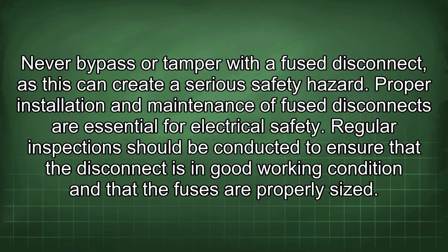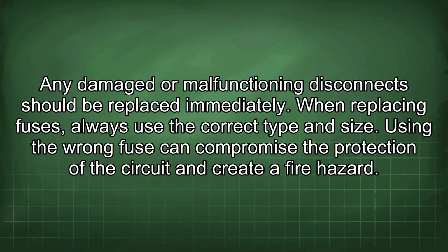Proper installation and maintenance of fuse disconnects are essential for electrical safety. Regular inspections should be conducted to ensure that the disconnect is in good working condition and that the fuses are properly sized. Any damaged or malfunctioning disconnect should be replaced immediately. When replacing fuses, always use the correct type and size. Using the wrong fuse can compromise the protection of the circuit and create a fire hazard.